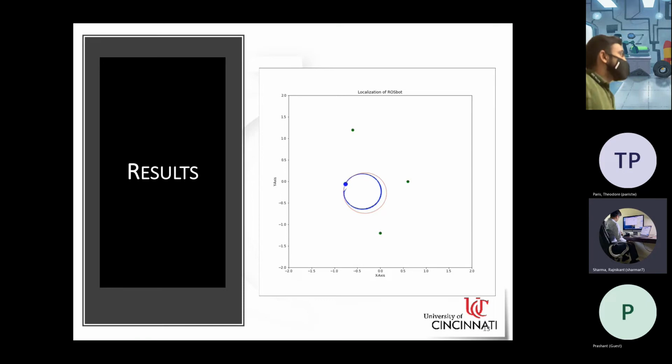So we gave the same initial condition for both true values and the estimated values. Seems like there is no correction happening there. See what I'm saying? The measurement should pull it towards the true value. It seems like it's going on its own prediction. Are you sure the EKF measurements were being updated?